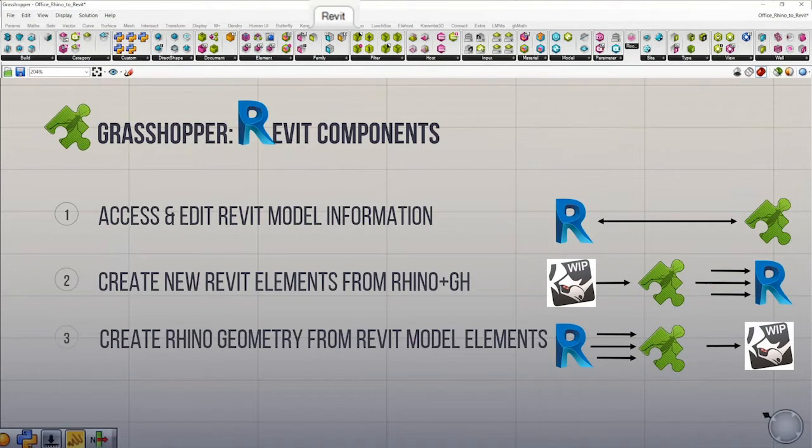So you can create the geometry, you can pull in the categories and types, so that you can then create and assign layers and sublayers and materials within Rhino. This may be a good workflow if you have a rendering program installed for Rhino, such as V-Ray for Rhino, but most of the project is in Revit, but you want to be able to visualize something at the completion of a certain stage of the project, and you would be able to do that with Rhino inside Revit by transferring all of the elements over to Rhino and then rendering from there.